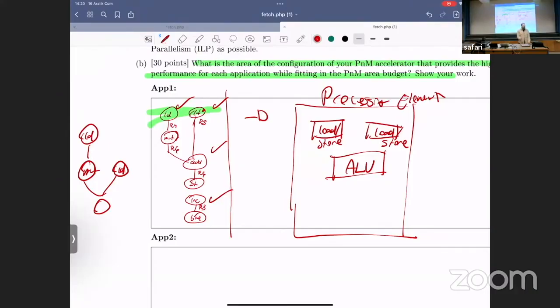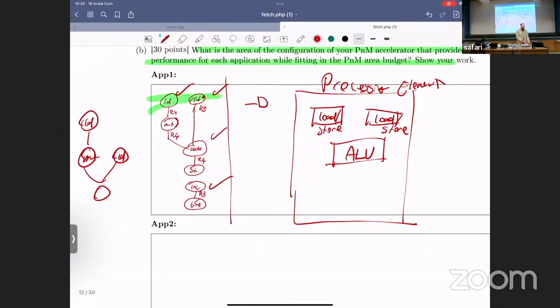The only parallelization you have is those load units, so the bandwidth depends on how many load units you have. It's quite important to do as many load operations as possible in parallel, so you can fully optimize the bandwidth of your DRAM.